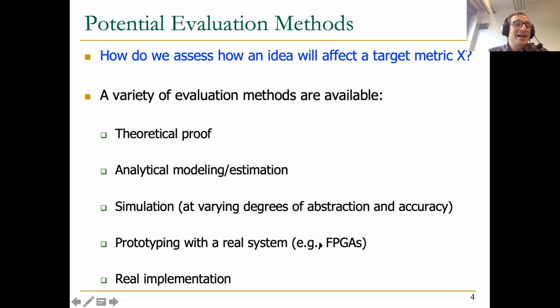And as a result, you may not actually be getting good, accurate numbers on an FPGA compared to simulation, where you're not bottlenecked by memory bandwidth. Or you can write your simulator such that you eliminate some of those bottlenecks and more accurately model what kind of memory bandwidth, what kind of memory latency, what kind of memory energy you would be getting if your processing units were actually inside the main memory itself, as opposed to the real system, which clearly does not have it. So this is a case in point, I think, to consider.